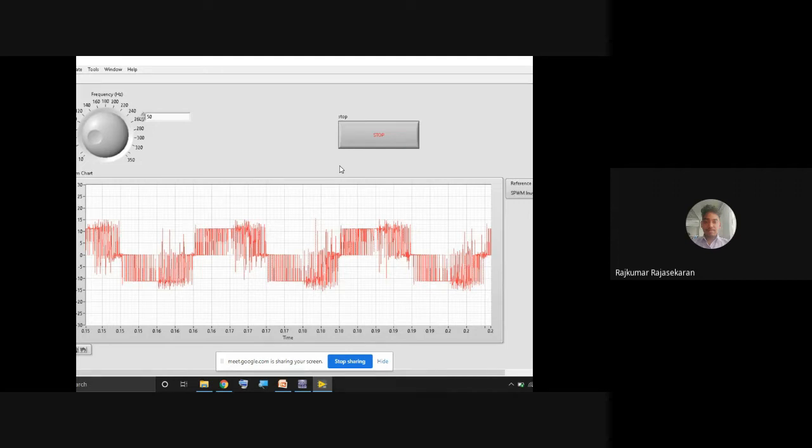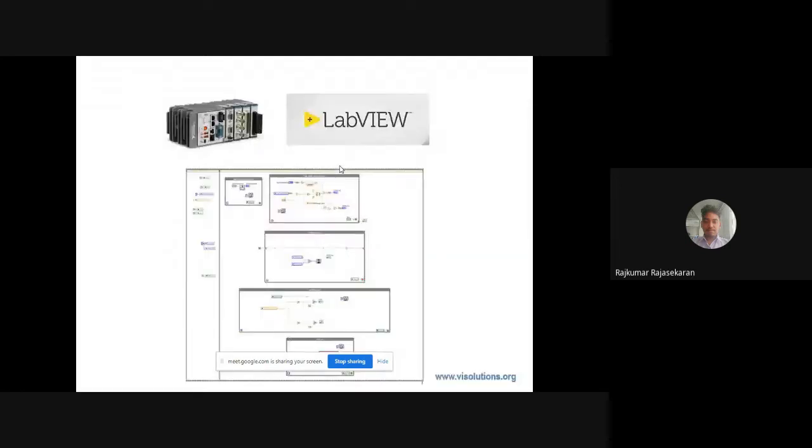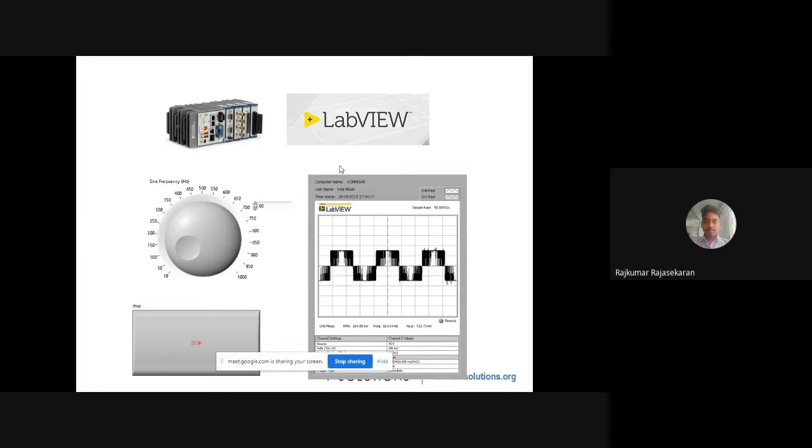So you can do real-time implementation and acquisition of an SPWM signal, and control the actual hardware using the CompactRIO, where the program could be written. You could acquire the data using the oscilloscope and display the data as an SPWM. Of course, we could add an LC filter and make it look much more sine-wave-like, but here we decided not to because we had to do some debugging. But yes, this is an actual real-time signal, which is 60 hertz because we generated a 60 hertz signal.